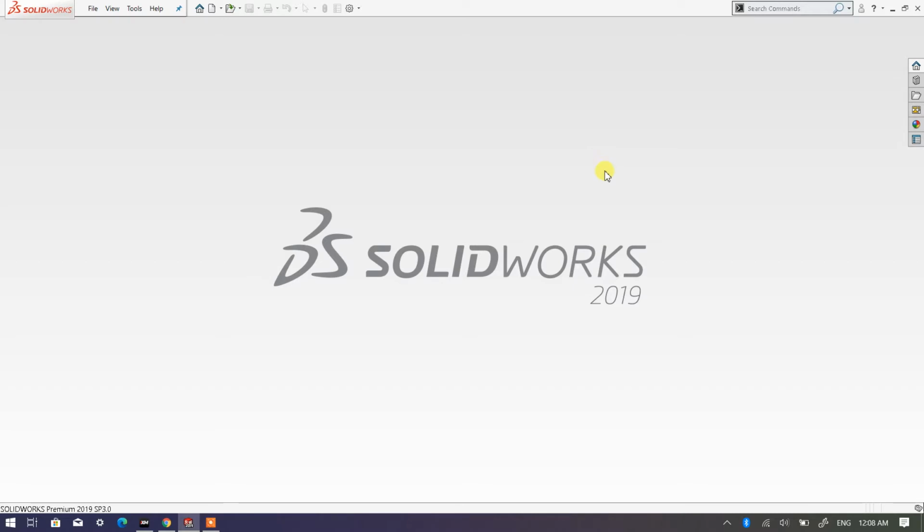In this video, I would like to share with all of you how we are going to apply assembly activities in 3D SolidWorks. We're going to create a few parts, whereby by using the mate command, M-A-T-E, mate command, we're going to proceed with the assembly activities. Okay, let's get started.